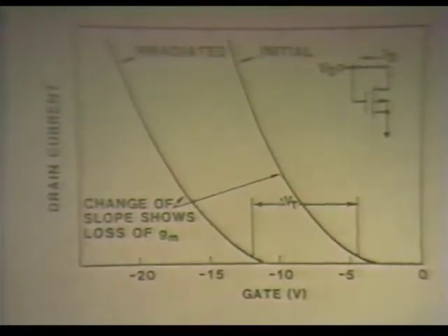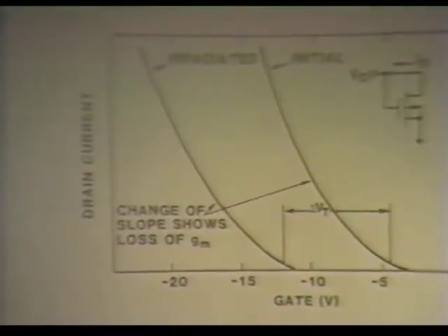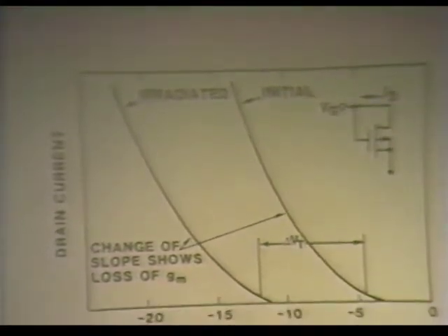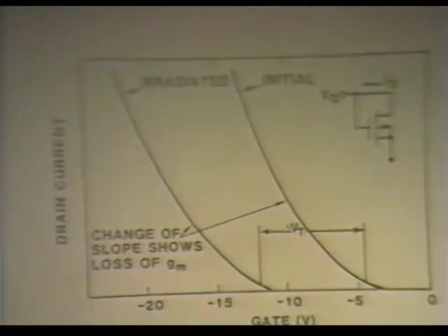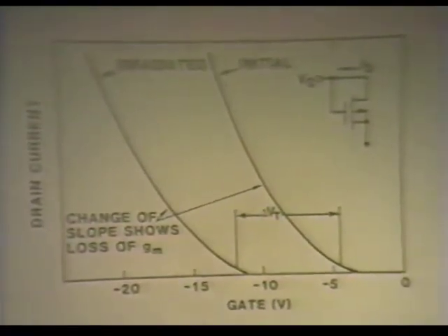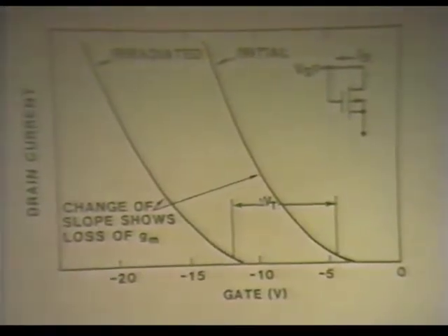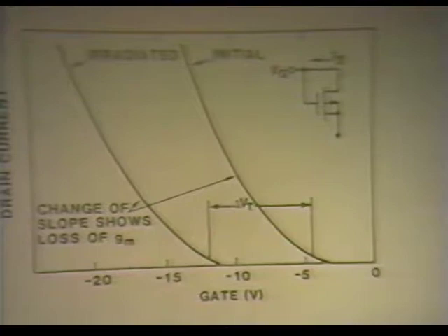In your CMOS or any of your MOS, what you've got is the gammas creating charge carriers that get trapped in the oxide and can't get out, thereby generating an internal field in the gate oxide, which counters or adds to the applied bias that you've got on the gate. And this continues to the point that the device won't operate anymore.